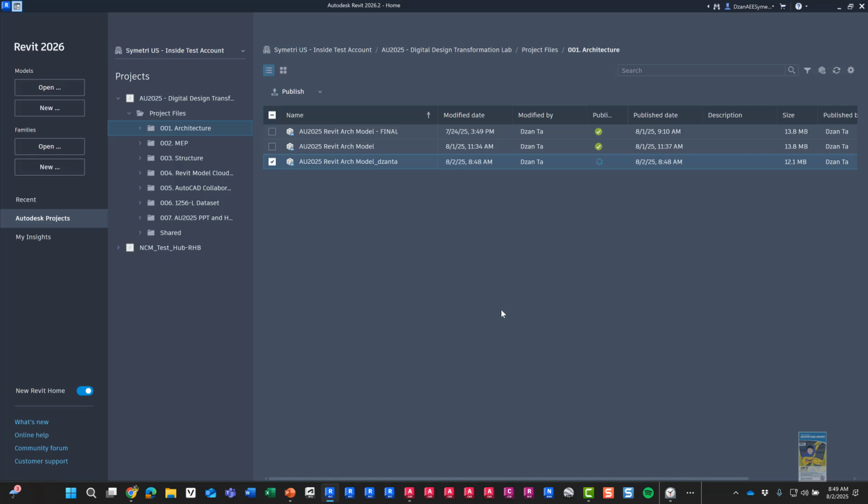Okay. When you're working with Revit on these Revit models within the application, you're actually working on the central model. There is a local model that is created. It is buried deep in your user's subfolder, and it is synchronizing with Revit Server back and forth to ACC so that it can do what you need it to do. It makes it a lot more transparent and easy for you to work with. You just basically go to the hub, to the project, to the folder, to the model, select it, and open it and work with it.